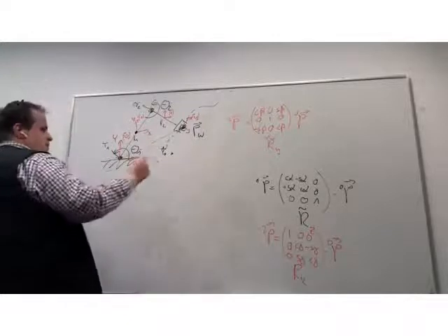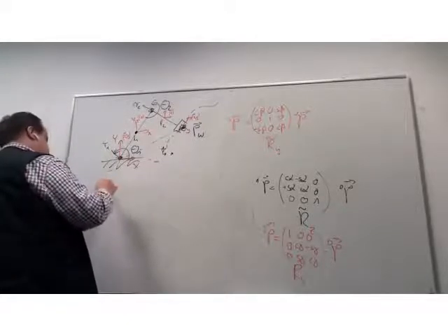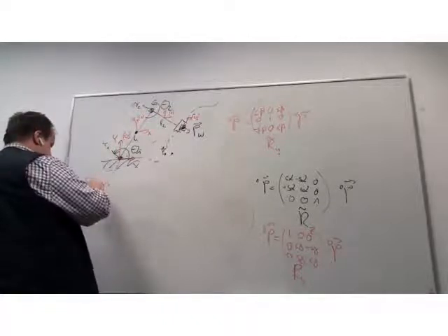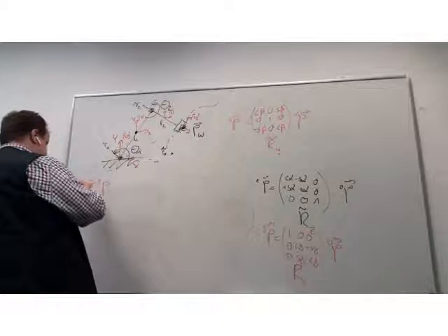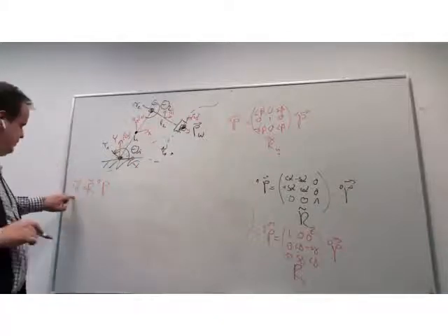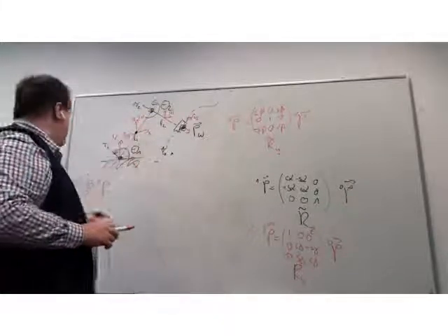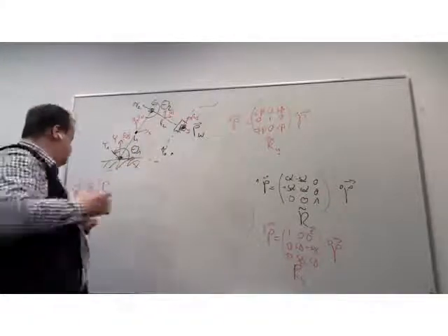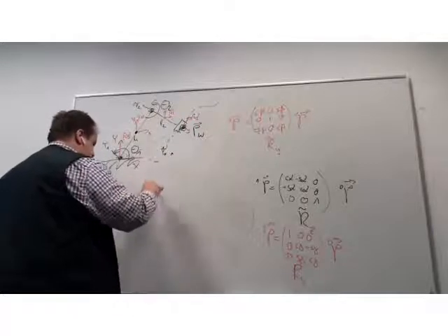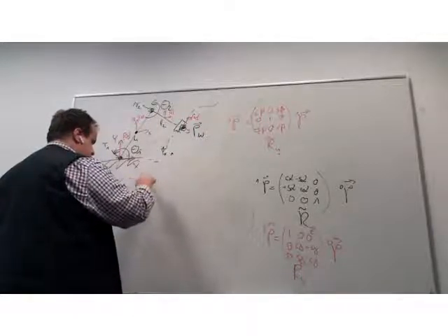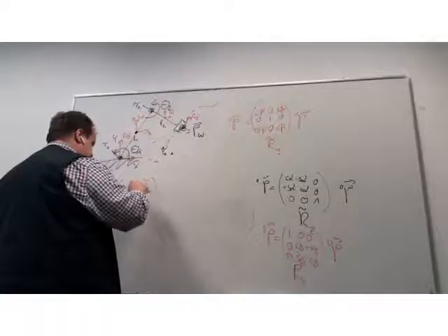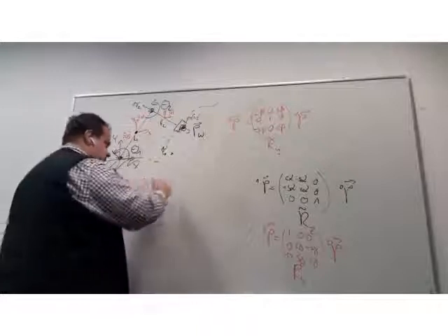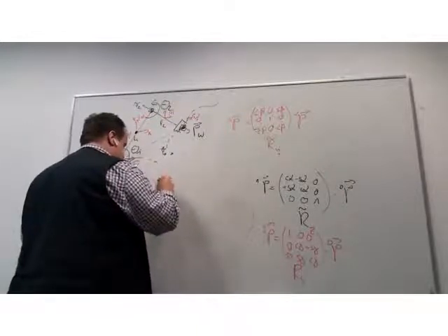We can now understand that if I have some point in link 0 and I'm applying a rotation to it to get a point in frame 1, we just defined that the orientation could be explained as a sequence of rotations around x, around y, and around z, applied to a point 0.